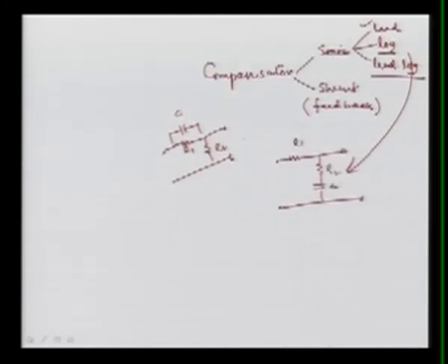So this is nothing but your lead compensator, and if you combine both, then we can get a lead-lag compensator. Now the feedback compensator is used to improve the robustness, or more stiffness to the load variation, and here we are talking about positive feedback. So feedback controllers are also one way. Now let us see how it can improve the system stability.